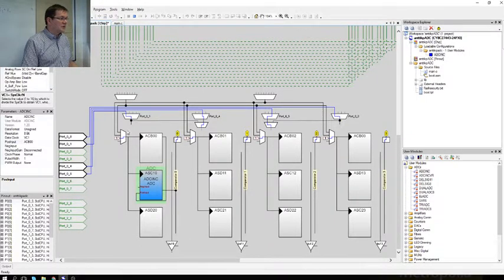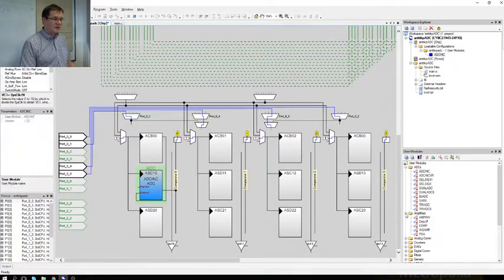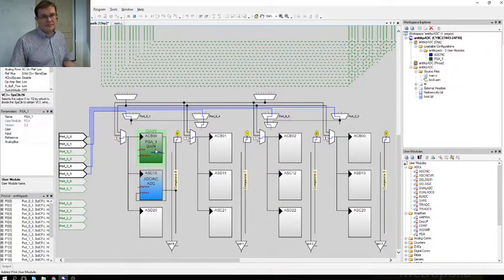But unfortunately, it doesn't have anything there yet. So for rerouting the signal, I can actually include there a PGA, which is programmable gain amplifier. Okay, if I take the programmable gain amplifier, now my A2D converter actually has a signal on it. We just need to now change some of the parameters.